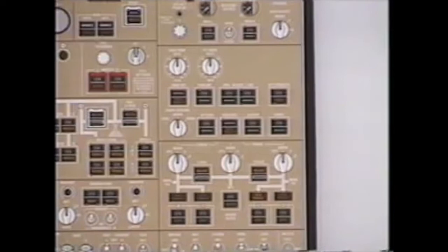So if a step climb was to occur between top of climb and top of descent, the packs would be in normal flow. If any pack for any reason shuts down, the remaining packs will instantly go to high flow. To determine the flow mode of your pack at the current time, bring up the ECS synoptic. Above the pack circle will be indicated high flow or nothing for normal flow.